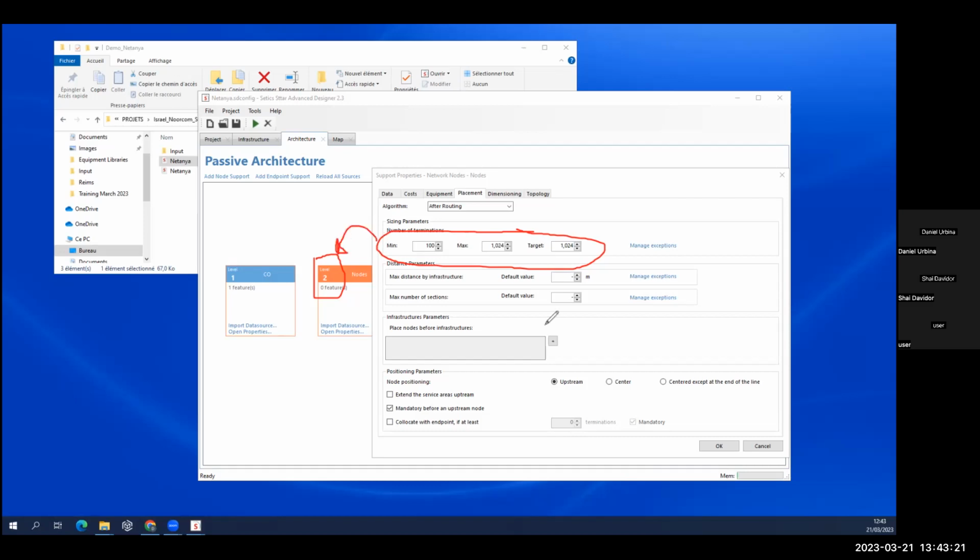So what are we defining here? We're not defining the size of a cluster, right? I am defining here the size of my level 2 cluster. So I can have several clusters. Each one will have maximum 1024 terminations, sorry. Right. That means it could be a few OLT ports. This is level 2. I have. Right. So what do I define there?